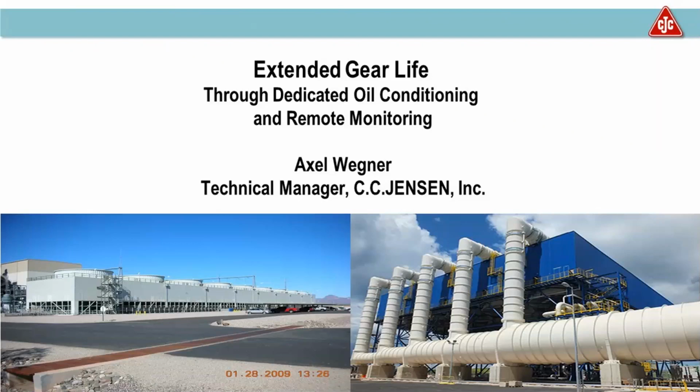From my side, I had some challenges to motivate, because initially when I specified that I wanted to procure new gearboxes with a 16/14 level of oil cleanliness, it was almost difficult to get it approved because they said it's too expensive to maintain such an oil cleanliness. So if there are other people that achieve less than 16/14/11, I would like to get some responses to say yes, we can achieve it.